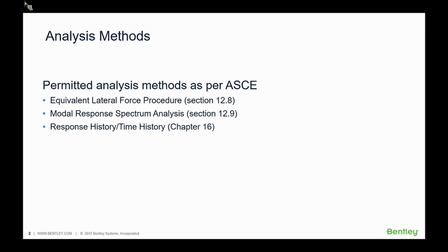The code permits engineers to carry out seismic analysis using one of three methods, namely the equivalent lateral force procedure as outlined in section 12.8, the modal response spectrum analysis method as outlined in section 12.9, and the response history procedure as outlined in chapter 16.